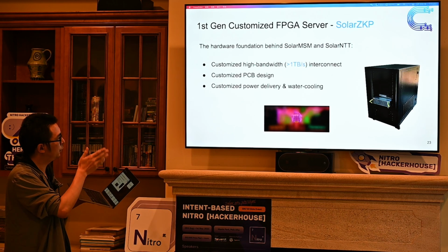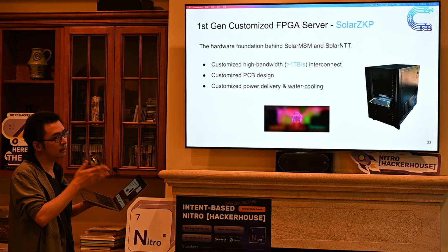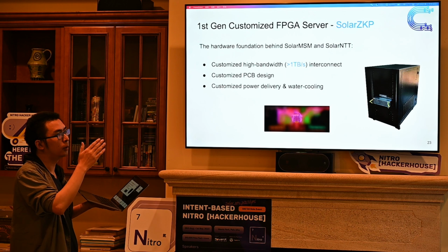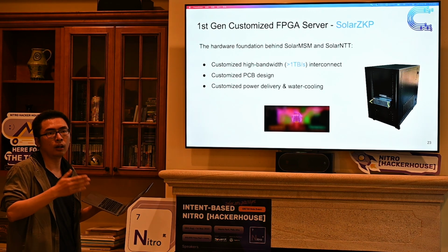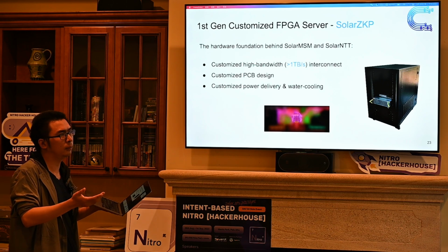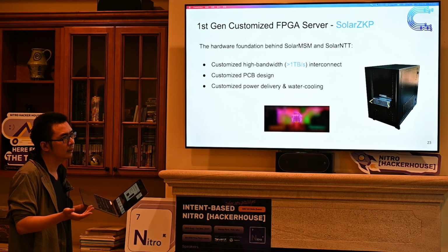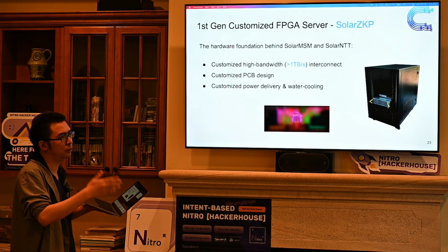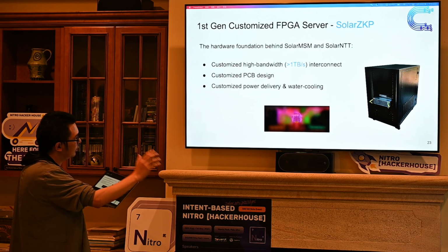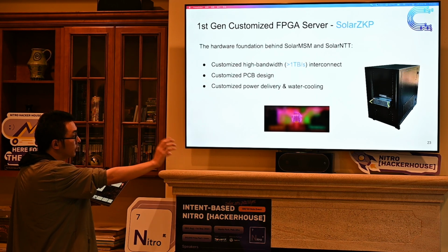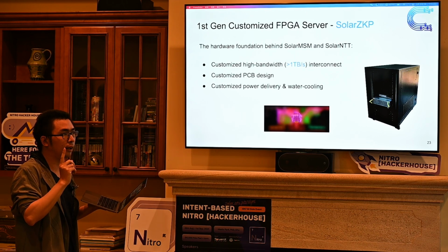The problem is this is too big, too heavy. So that's why we are developing an ASIC design on top of our FPGA implementation. FPGA hardware itself is not so efficient, because to make the hardware reprogrammable you lose so much. For example, your frequency is restricted to 300 megahertz. So in the next step we are going to squeeze all the computation power of that machine into a single accelerator die.